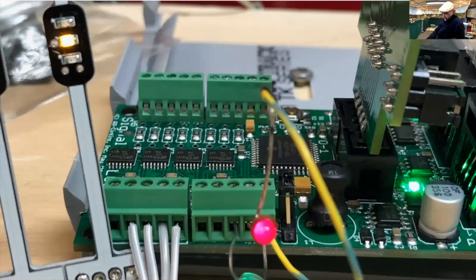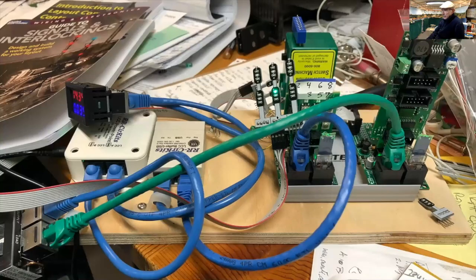This is just a close-up of the LCC signal board. Each of these terminals is involved in powering the LEDs. And the one in the end is the ground wire, and then the rest of the ports here are for the individual LEDs. You can see here I have the yellow light illuminated, which means that there's power between the ground here and the middle wire here. In this case, I was able to change it to the green wire. I also, you can see amid the mess here, I'm getting ready to try powering a switch machine, which will be a whole other part of the process.